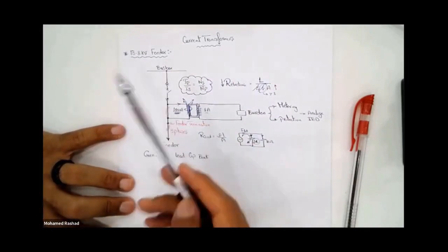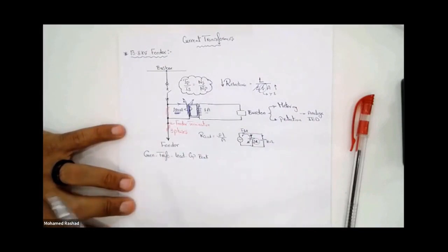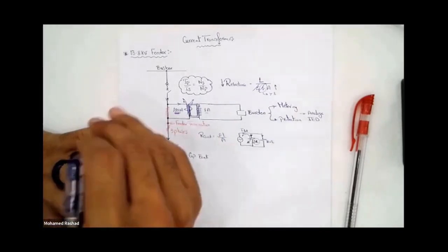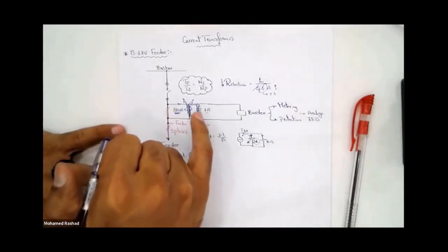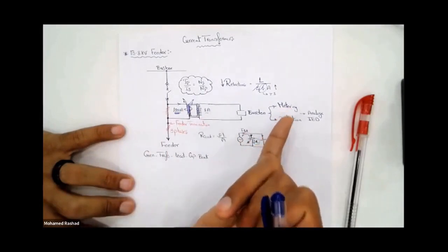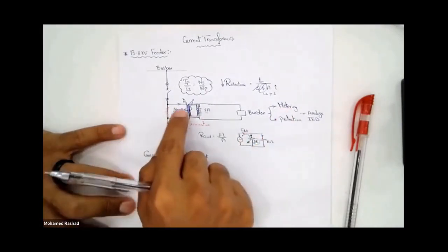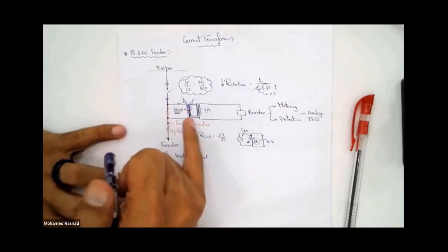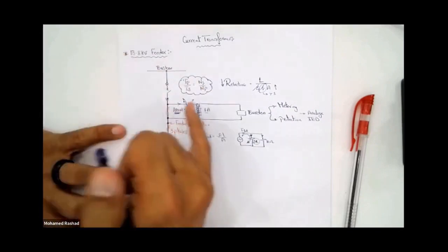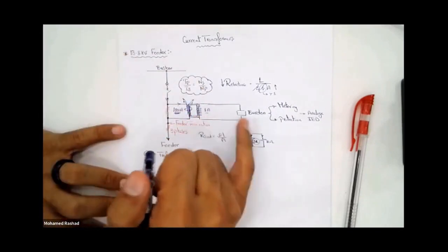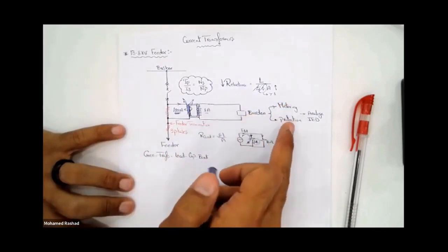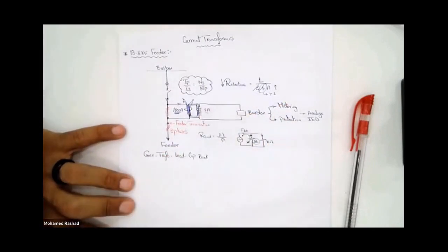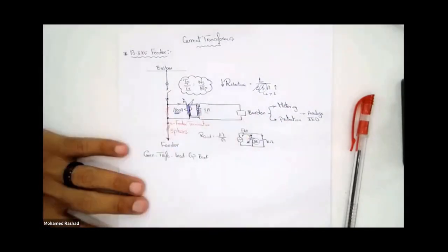The current transformer is one of the types of measuring transformers. For static machines, its purpose is to reduce the current to values which can be handled by metering and protection devices. The second thing is that its primary winding is connected to your power network, and its secondary winding carries the reduced current that you connect to your load, whether it's a meter or a protection device. So here you are dealing with lower values, which makes it safe for you and the equipment present. All right, great.